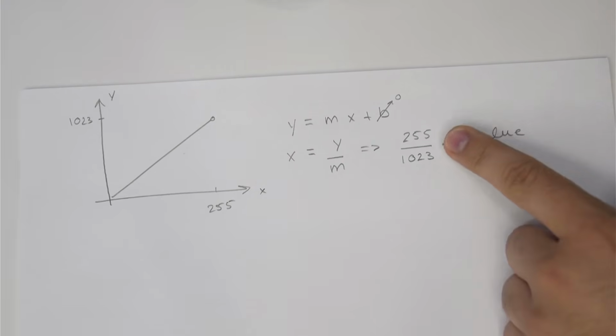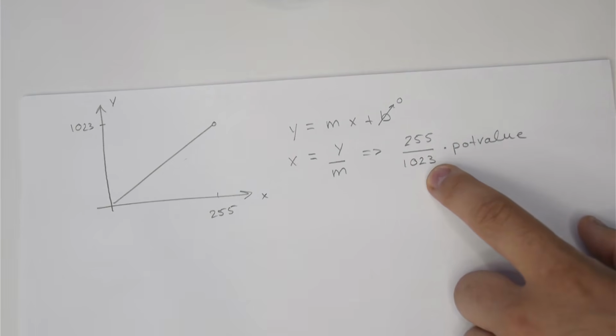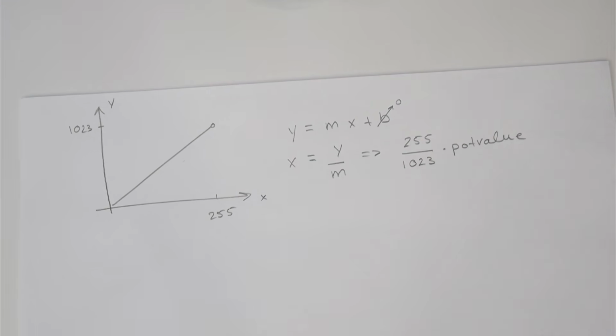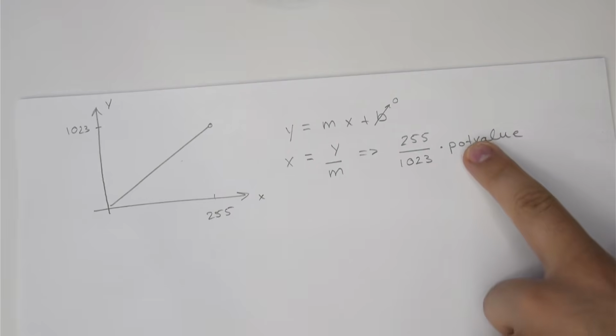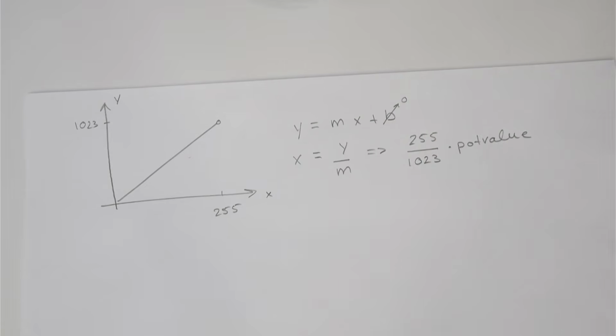Now, you can't simply do this in the C code because of integer division, this will result in 0. This will cause some problems. So what we'll have to do is assign this as an unsigned long and then do the division and then set it into our X value. And it's quite simple when you want to do things like that. So I'll go back to the code.